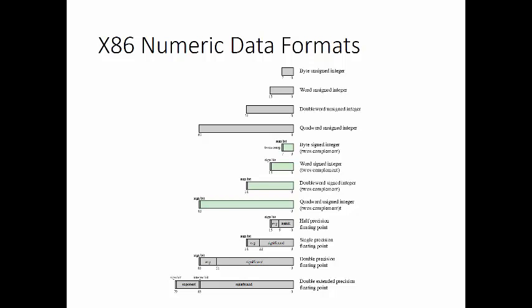Normally, half-word access should be half-word aligned, and word addresses should be word aligned, so you don't have the ability to have things that are misaligned like you do in the x86 architecture. Although it does support 3 alternatives if they're not aligned. The default case, it's treated as truncated. There's also alignment checking and unaligned access. With the unaligned access, when that's enabled, the processor uses 1 or more memory accesses to generate the required transfer of adjacent bytes to the programmer.